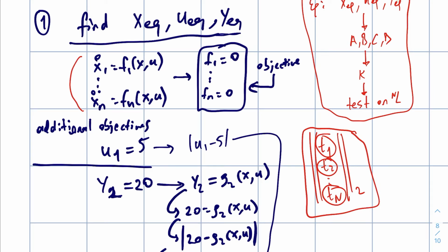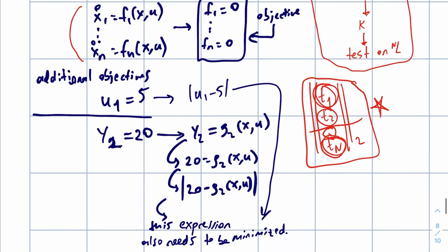For example, the first n terms might be your x dot terms, and after that you can impose your input related constraints, and additionally you will have output related constraints, and you can just stack them up together, and the resulting expression is the term that you take as the cost. By changing x and u, you minimize this cost term. So let's move on and focus on the output constraints.